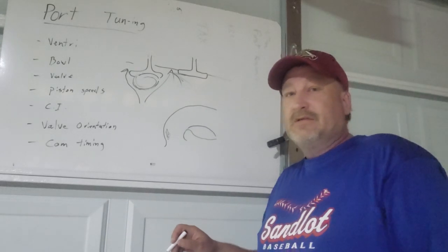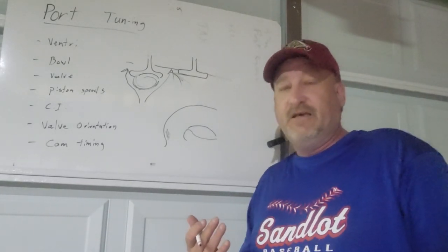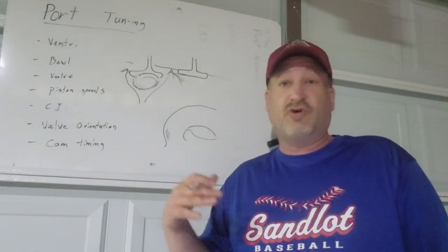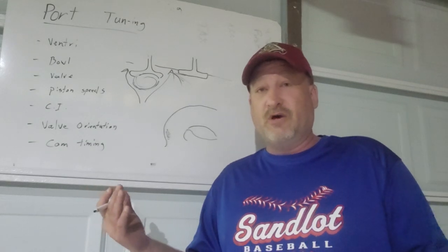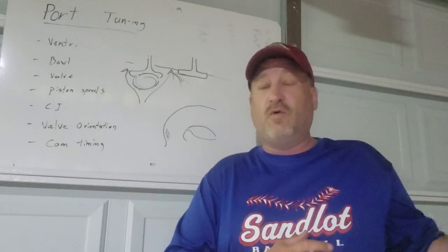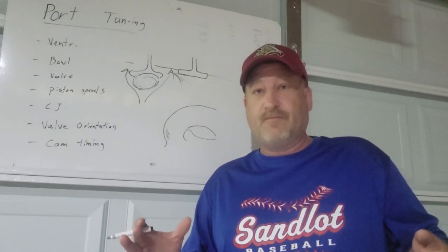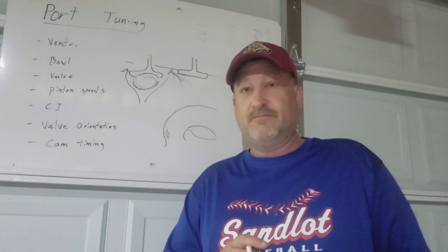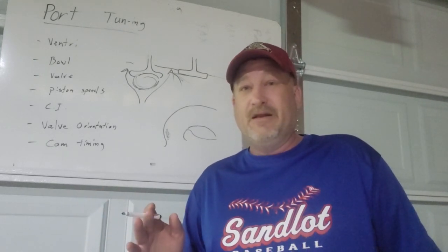Okay, so in order for the Oldsmobiles to get the efficiency of fuel mileage compared to the small block Chevy, it has to occur at a higher RPM. So if you compare a 350 Chevy compared to a 350 Oldsmobile at 2,500 RPM, the small block Chevy will get better fuel economy. It does.